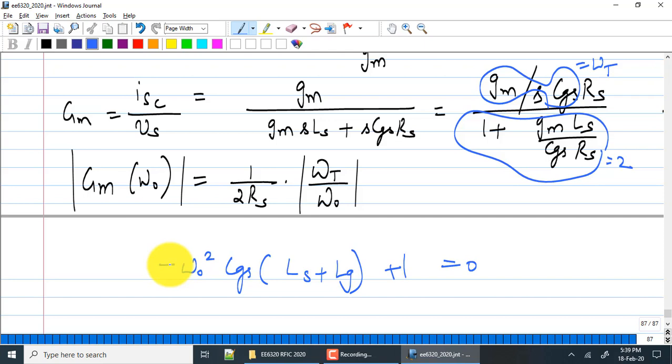At this frequency, okay, you can see that the effective transconductance of the device is actually independent again of a lot of things. It's independent of device parameters almost, except for omega t. Okay, it is not dependent on other parameters. It is not dependent on Ls and Lg directly at all, except for the fact that product of omega t and Ls has to be Rs. Right? Everything is kind of captured here. It assumes a lot of assumptions.